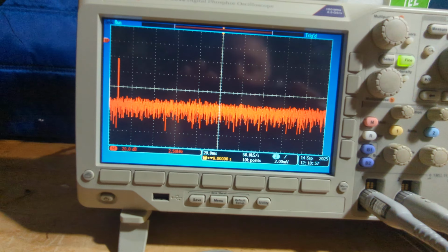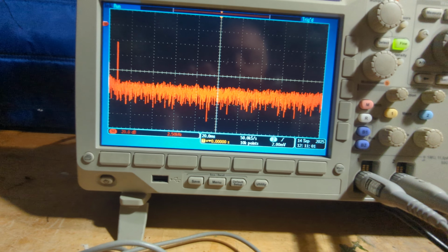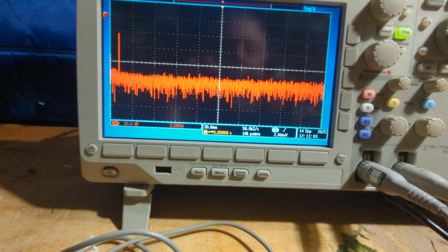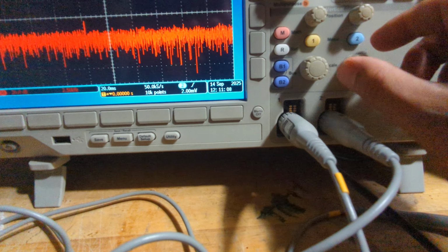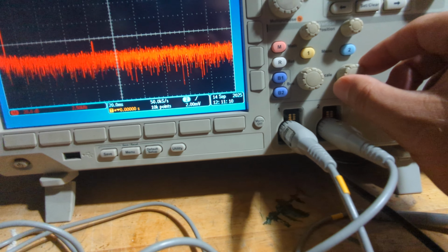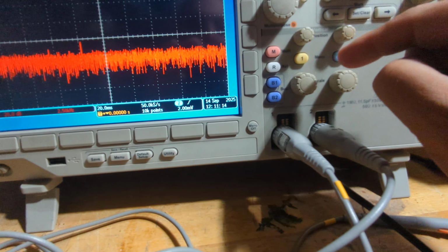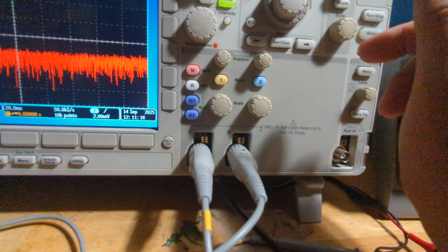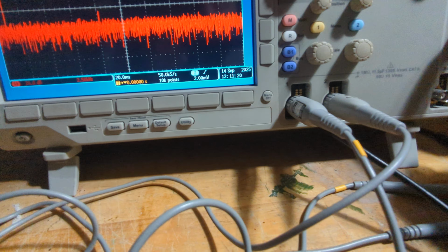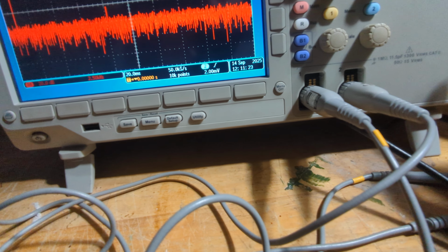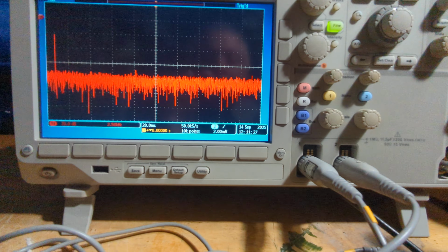So that really is how to use the oscilloscope. This is time, this is voltage. These buttons here zoom in on voltage, zoom out on voltage, and move things up and down. Over here expands or zooms in on time, and then you have the trigger, making sure that the trigger is inside your repeating periodic waveform.